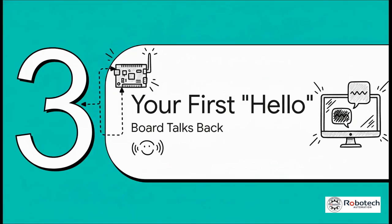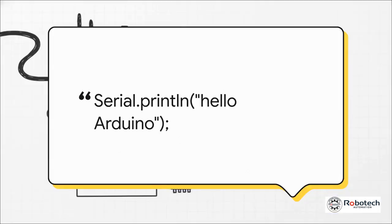Let's get that first little victory and make the board talk back to us. This is how we'll know for sure that everything's working. And the command is super easy. It's just Serial.println. Whatever text you stick inside those parentheses and quotes, that's what your ESP32 is going to send back to your computer. That ln at the end just means line, so it adds an enter key at the end to keep things tidy.